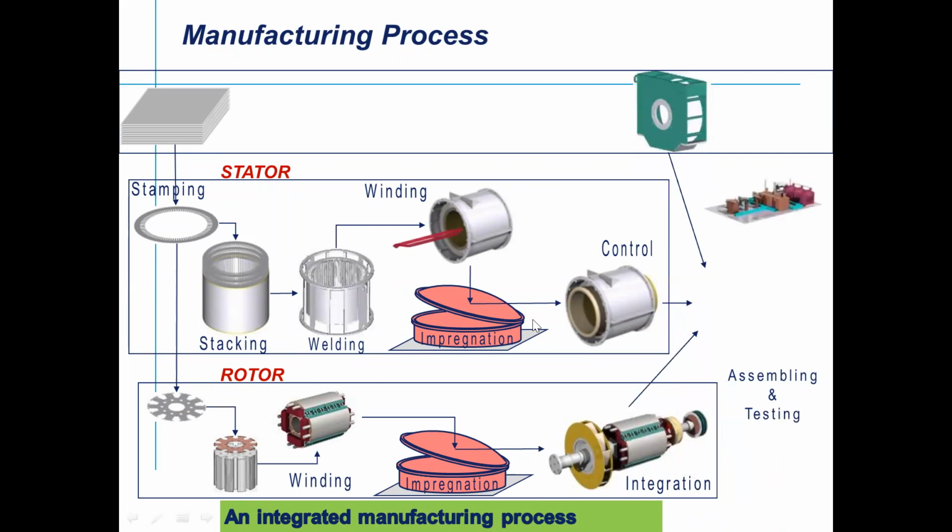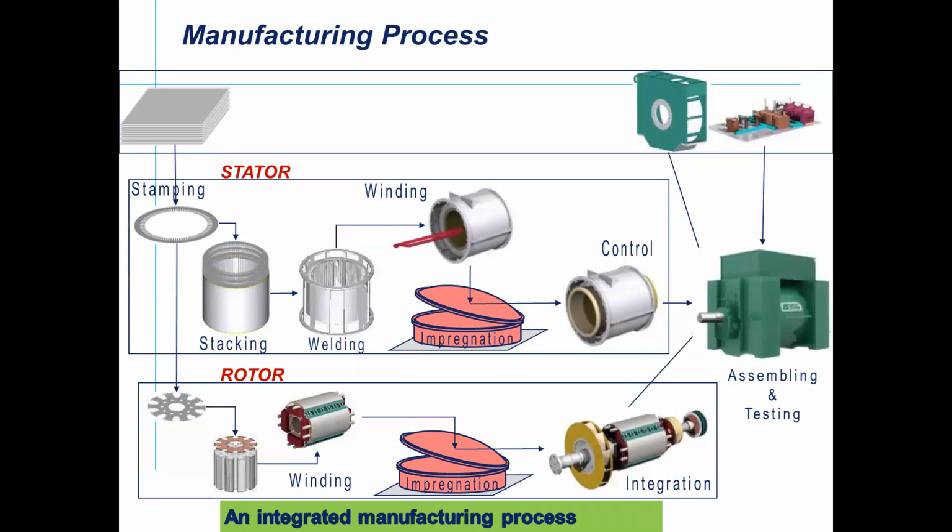So this is a machine prepared in a system where you can see the stator assembly comes in one area, and the rotor assembly follows the same process. You can see the stamping built into the core, and after that the copper winding is done on each pole. This is a 4-pole, where you can see the 4 windings, and again it is going to be a VPI process. Once that is completed, you can see the rotor assembly has been built like that.